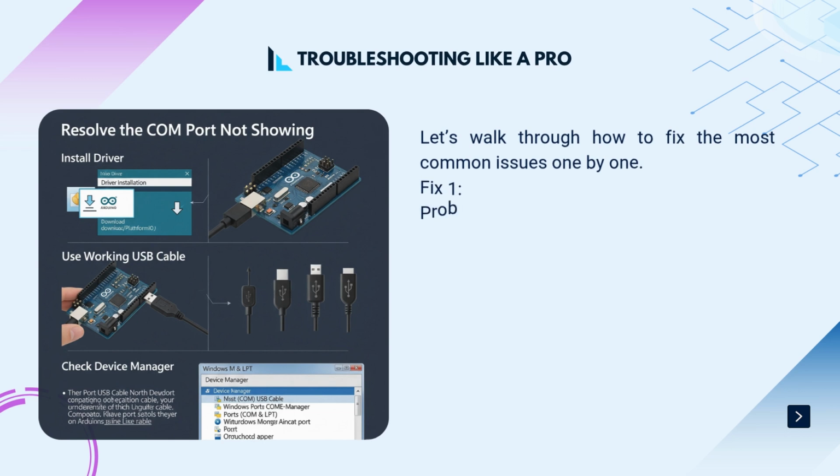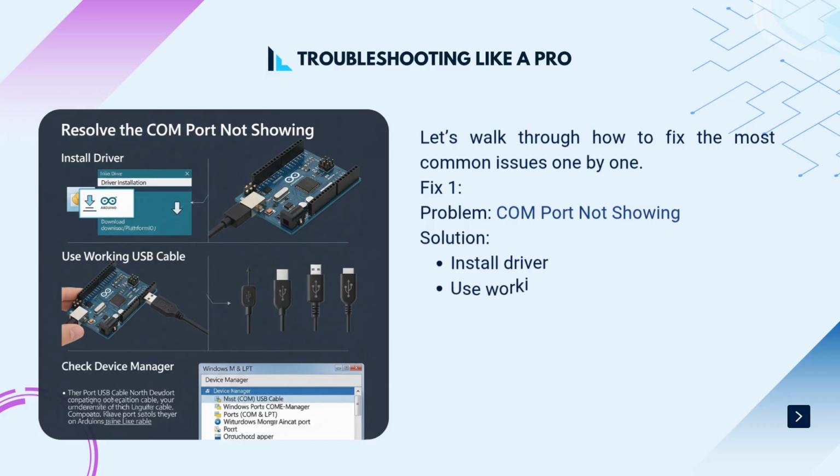Here's how you become a flashing ninja. Case 1, COM port not detected. You plug in the board and nothing. First, test with a different USB cable, ideally one you know works with data. Next, check Device Manager on Windows or ls /dev/tty* on Linux. Still nothing? Try reinstalling drivers or switching USB ports.